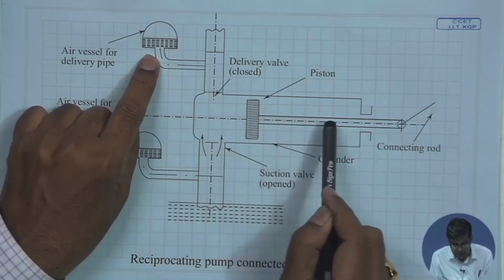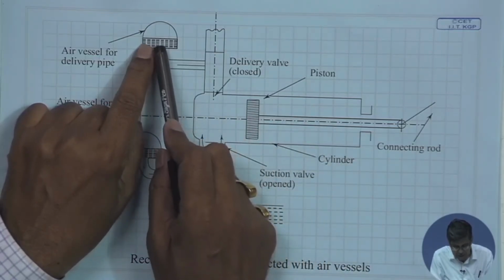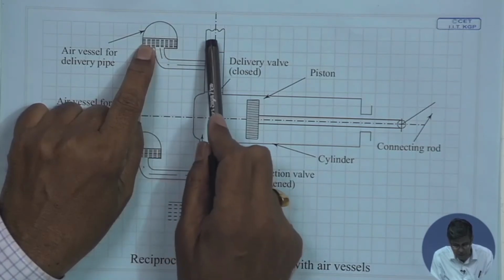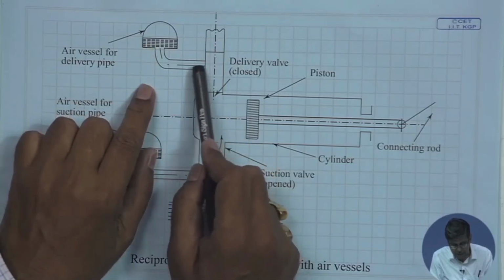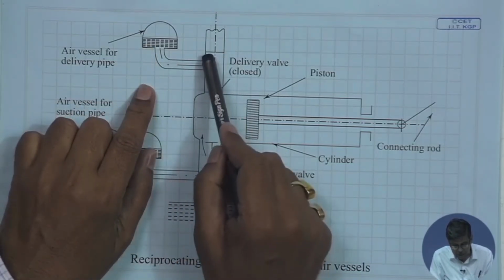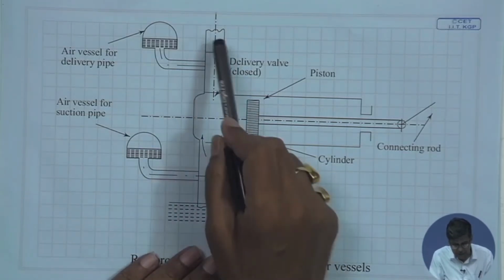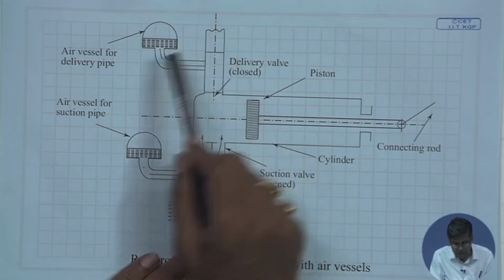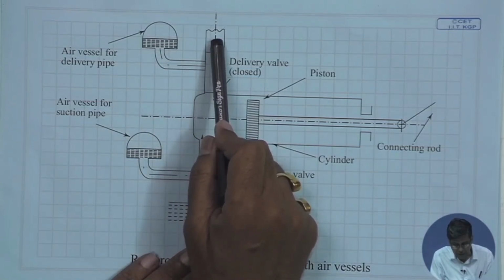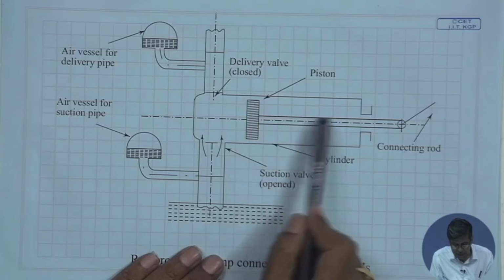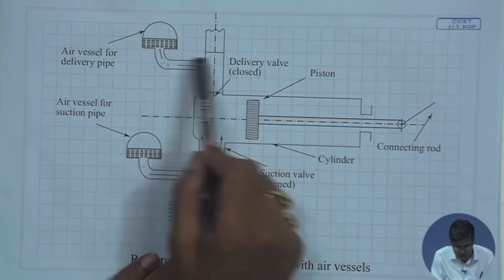When the initial acceleration is high and the discharge rate has to be more, this releases water and goes like this, and the similar thing happens at the end of the discharge period. So, therefore, the rest part of the delivery line, similar to the suction line, gets uniform discharge because of this air vessel. It gives additional water required in the initial part of the delivery stroke because of the acceleration head, and similarly takes water to reduce it.